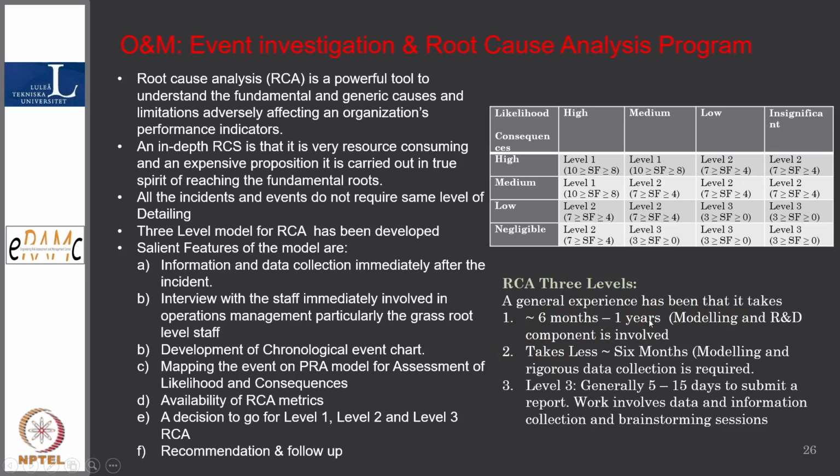Okay, so then other salient features of the modeling are information and data collection from the incident site, interview with the staff immediately involved, and where, like if it is round the clock shift, who are the operators manning the area, mechanics. So development of chronological order of events, how the events have happened, mapping the event on PRA model of the plant. So it is called precursor analysis, and try to understand the consequences from there.